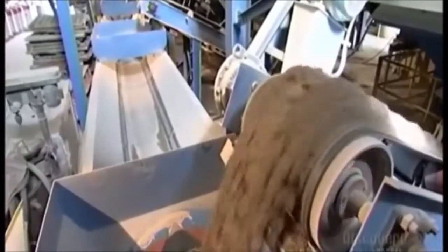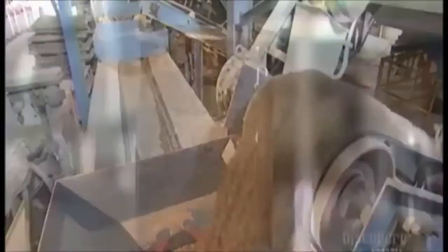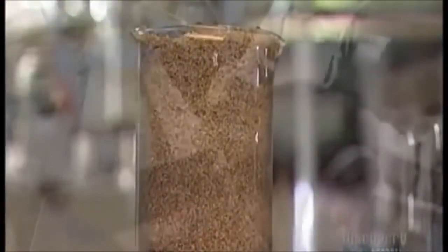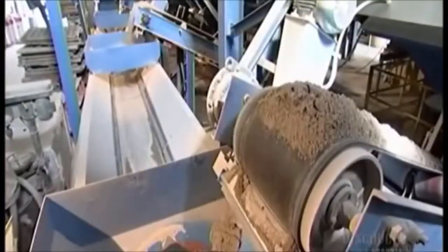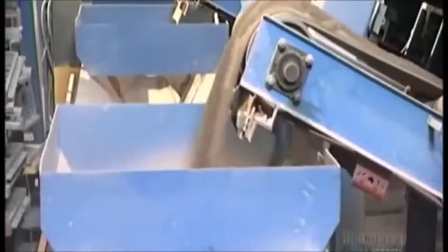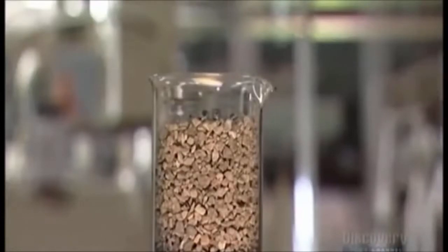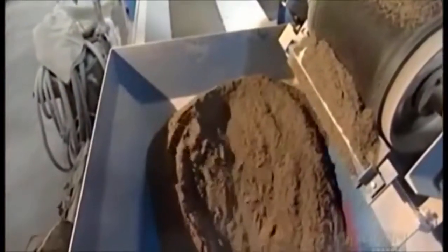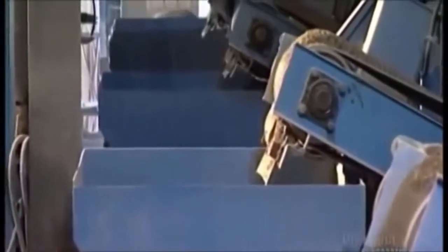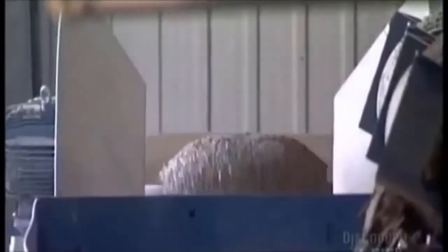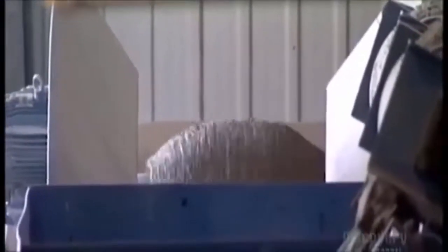To make these pavers, a conveyor belt delivers concrete sand to a weigh belt that weighs the coarse sand as it falls onto it. The weigh belt carries the sand forward, while another conveyor belt unloads stone chips to be weighed. These chips are no larger than 1/3 of a centimeter. The ratio of sand to stone chips varies depending on the type of paver being made. The weigh belt transports the stone chips forward along with the coarse sand.